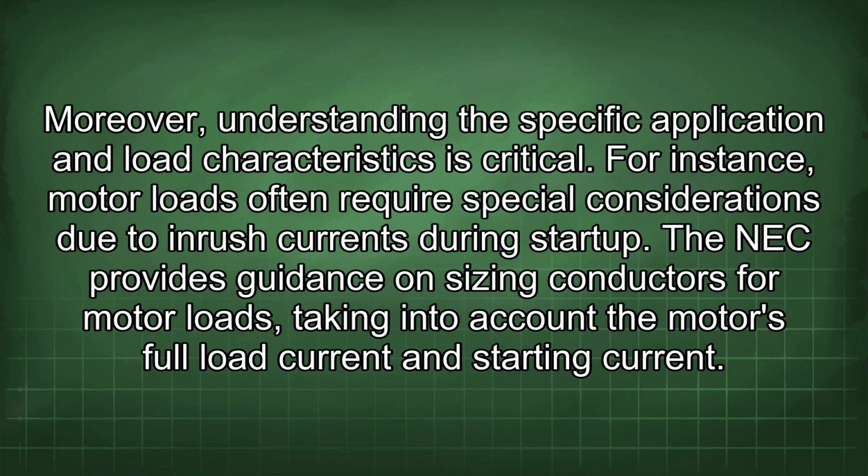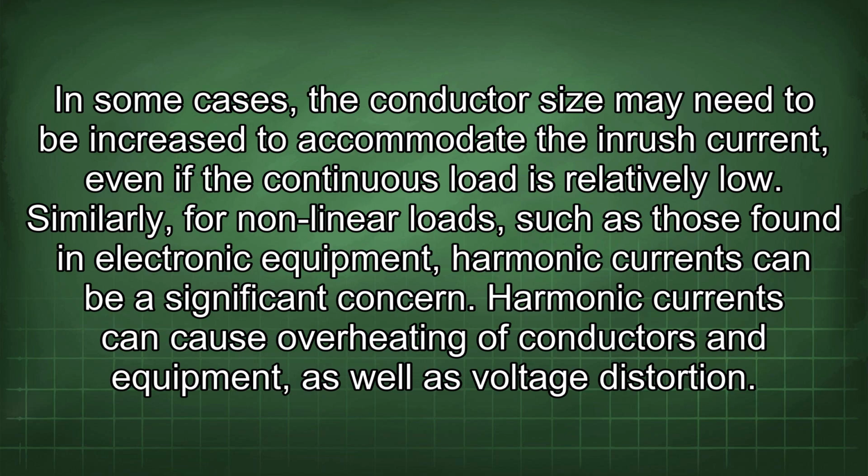Moreover, understanding the specific application and load characteristics is critical. For instance, motor loads often require special considerations due to inrush currents during startup. The NEC provides guidance on sizing conductors for motor loads, taking into account the motor's full load current and starting current. In some cases, the conductor size may need to be increased to accommodate the inrush current, even if the continuous load is relatively low.